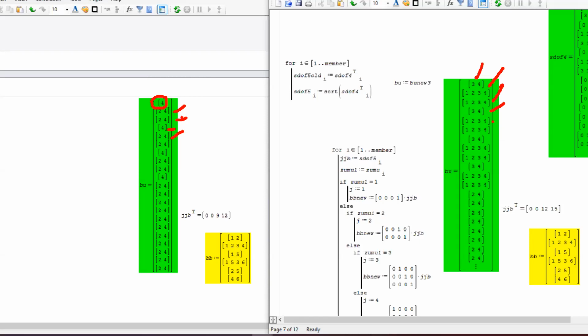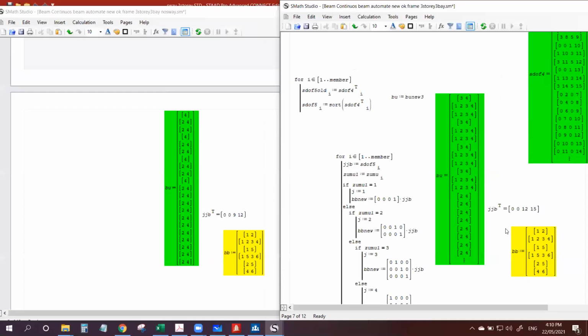For member 5 in the sway frame, I already need all of the data there. While for the girders, it's the same: two data only, because again, no vertical displacement, because no axial deformation on the column. Only rotation.